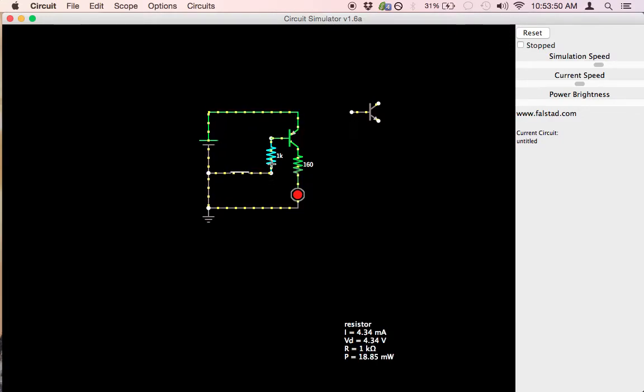This limits the base current to approximately 5 milliamps, and then through our closed switch back to the negative terminal of the supply. If we open this switch, we will break this circuit and no current will flow through the base emitter junction. You can see that there's a positive voltage available to the emitter and in the base and all the way through this transistor, but because our switch is open, there's no actual current flow. We have a positive voltage but no current.